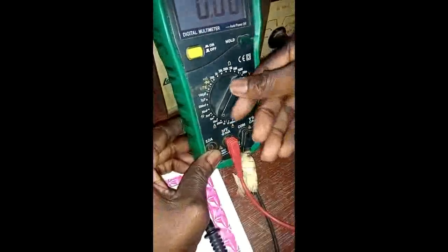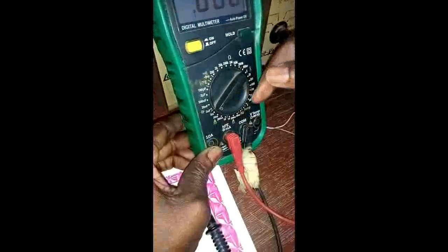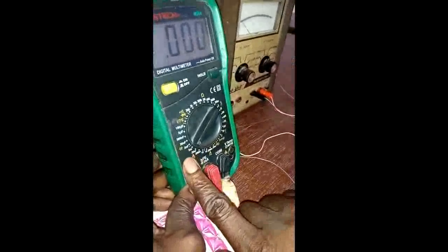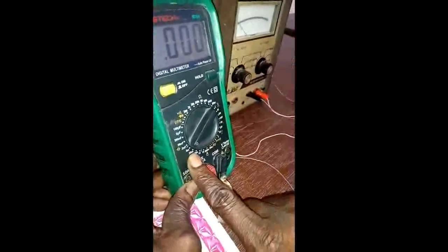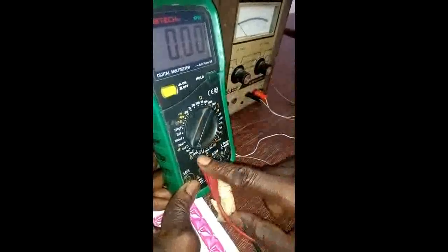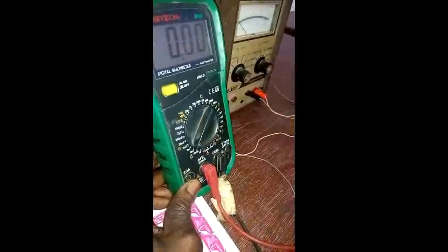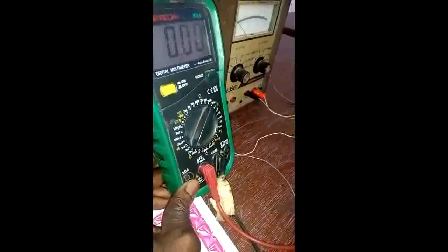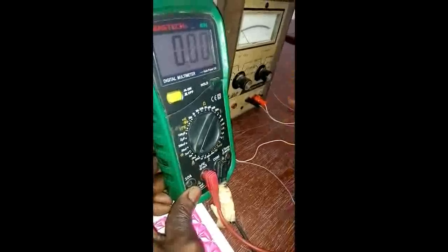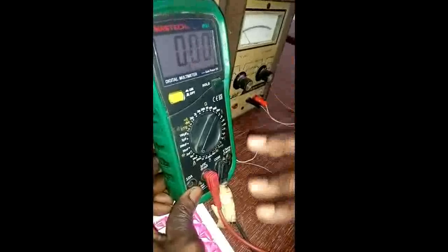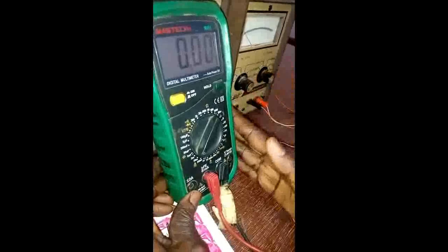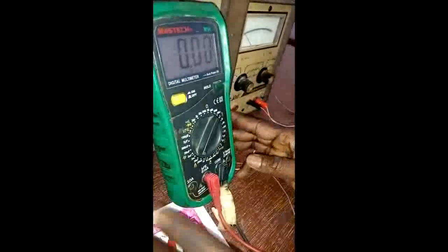So like this one now, if you want to use it to measure current, DC current for that matter, the minimum is 2 milliamp. Next is 20 milliamp range. The manner we guide you, you have to set it anyway. Then another one is 200 milliamp. And then you only need to read it. You don't need to do any calculation from your head. Or like when you are using analog meter, you still need to do multiplication, you divide, you do all sorts of things. But this one, that is the advantage digital multimeter has over analog multimeter.